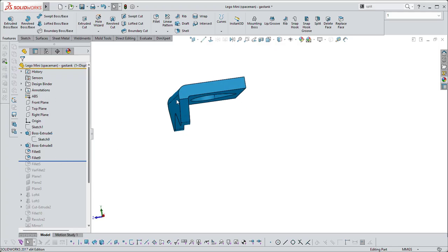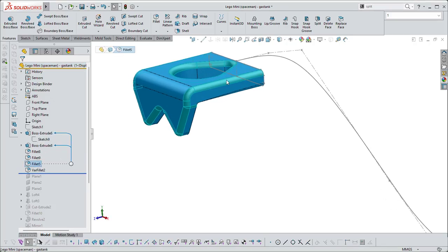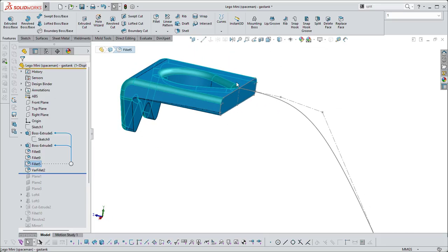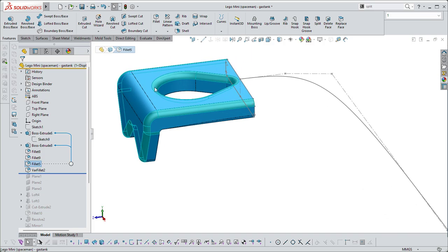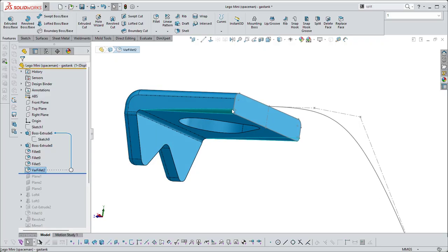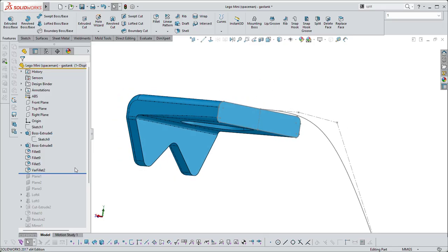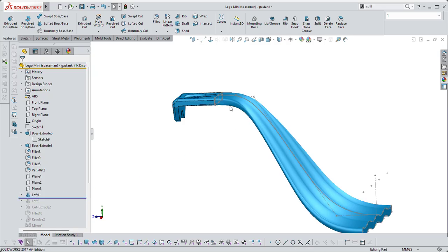So that gives me my major geometry, and then the minor fillets are this fillet going around the outer edge, only to that point, because I want this face here to be flat so that I can extrude from it, loft from it. And then this variable fillet, I won't show you how to do that right now, but that goes from 0.3 down to 0, so that this face has rounded edges all the way around, so that when I do a loft, it doesn't have any sharp edges. Right, then to the loft.